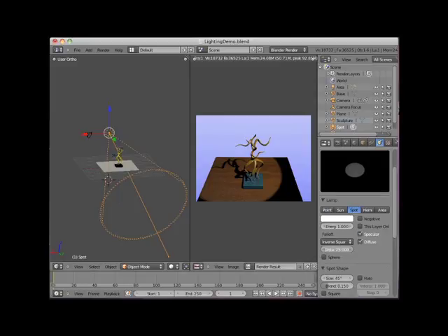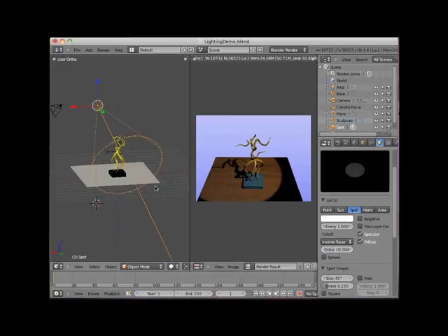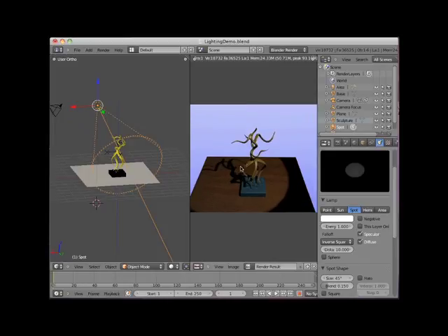Note that as the fall-off distance control is changed, the length of the spotlight cone represented in the 3D viewport changes accordingly. Here I will set the fall-off distance to 10 Blender units and render the scene. Because the fall-off distance is shorter, the illumination of the objects is dimmer because the fall-off is quicker.